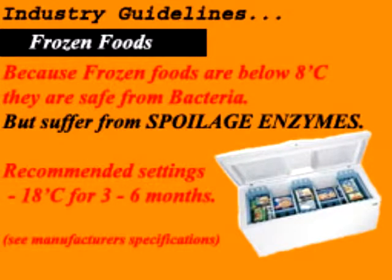The recommended freezer settings for most light or medium duty foods are minus 18 degrees Celsius. This temperature slows down the effect of spoilage enzymes significantly and holds most foods without spoilage, subject to the manufacturer's instructions, for between 3 to 6 months. Larger food producers, however, may need a longer term of protection for their foods, and their freezers are often set to -24 degrees Celsius. At this temperature, the spoilage enzymes almost totally cease to have any deteriorating effect.